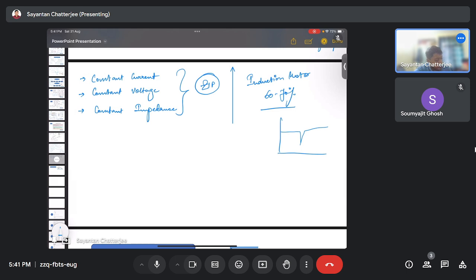So in the load flow studies we generally take into consideration that since the loading scenarios are highly dependent, we take care of the values of P and Q, and mostly they are taken to be constant load models, constant values. But here we are also seeing that the loads are of current and voltage or impedance type. But in load flow studies we generally take constant values. This was the problem I was trying to say some days back.